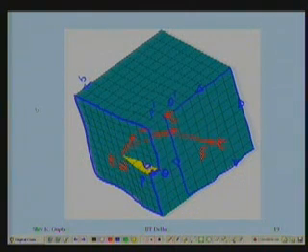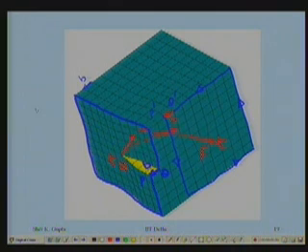Why is it so? Why the Burgers vector is invariant? Whether I take this shape of the slip part or I take some other shape of the slip part, the push which I have given is the same constant. Push is the constant. Direction and magnitude, that's a constant.